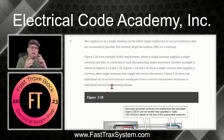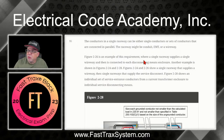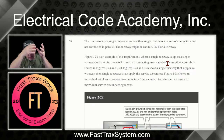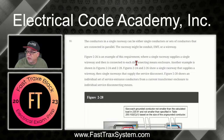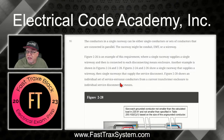It is an example of the requirement where the single raceway supplies a single wireway and then is connected to each disconnecting means enclosure. So you saw it went from one raceway coming in, went to one wireway, and then it broke off to two separate service disconnecting means enclosures. Another example is shown in 2-24 and 2-28. Well, we'll stay at 2-28 because 2-24 is kind of the same scenario.